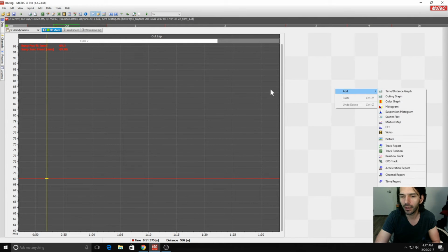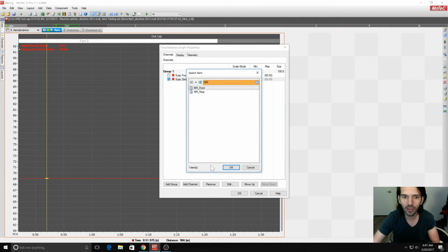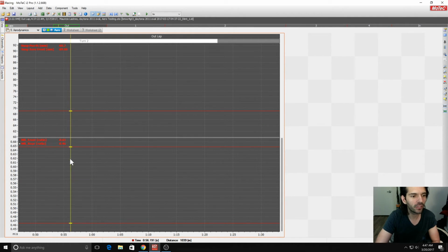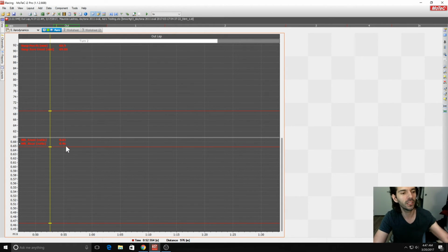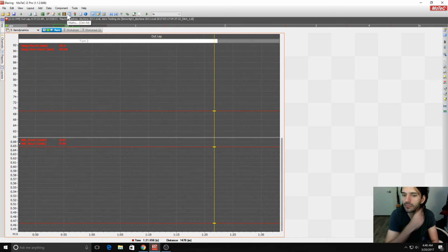So let's see, like MR. Let's collect these two. And motion ratio in the front is 0.65. The motion ratio in the rear is 0.46. Those are reasonable numbers. I would love to know if that is actually correct for the BMW Z4, but they are definitely in the ballpark for what a real race car would have. So we calculated those two values at 60.